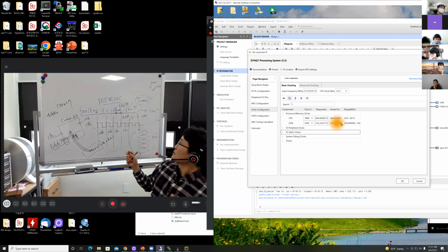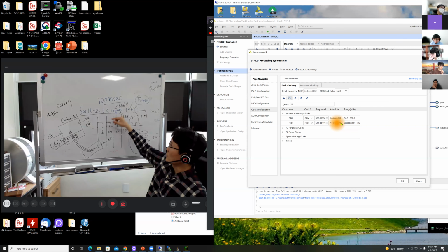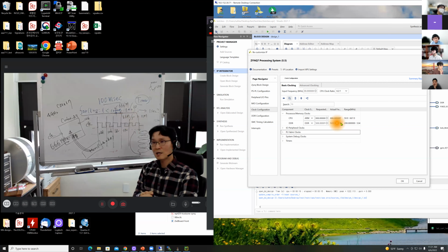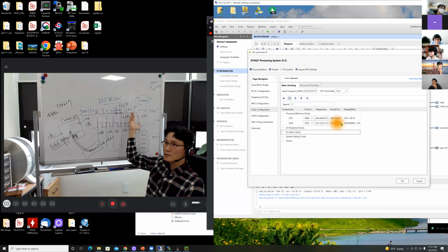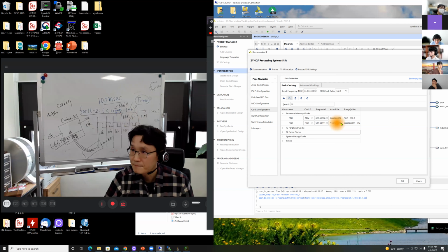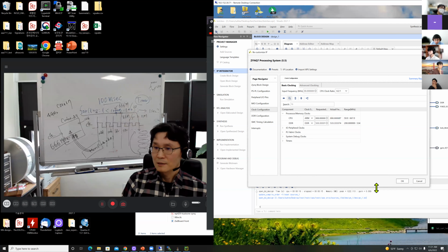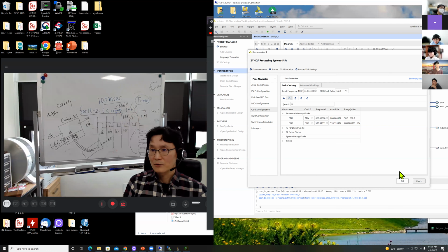You can determine this count. Play with the count, right? This is trial and error. You play with some number and measure the time with your watch. Then if the time is not good, reduce or increase. Trial and error, right? Okay, that's what you can do until we study timer, the hardware component, the timer IO device.